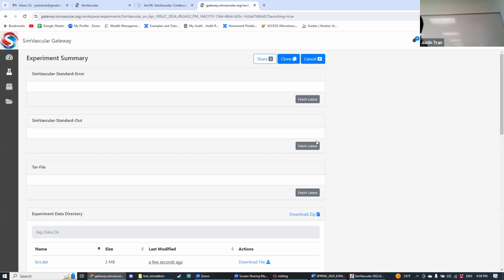Sure. Let's say I didn't get a pass, but it could have been good. Would you recommend changing the model to fit your comments? Yeah, definitely. I think for your model in particular, you're going to have some trouble with the meshing, since the surface is rough. So I would definitely try to smooth it out.